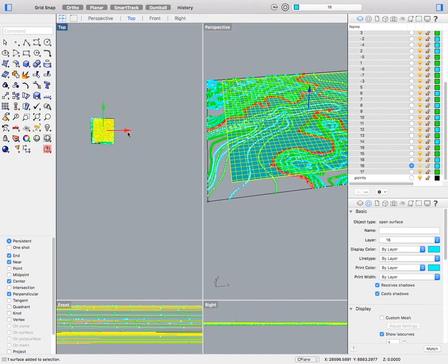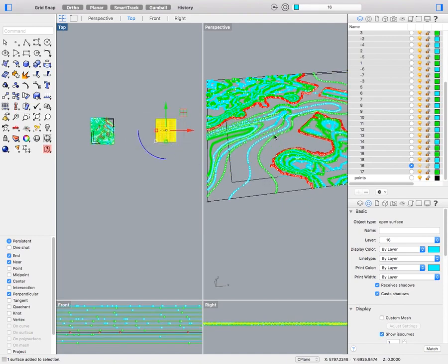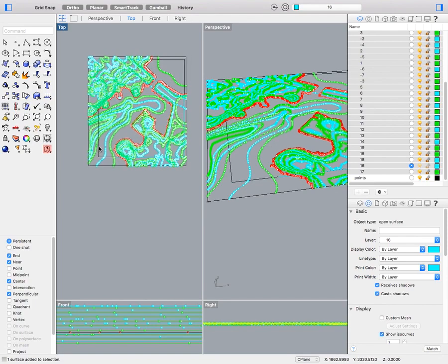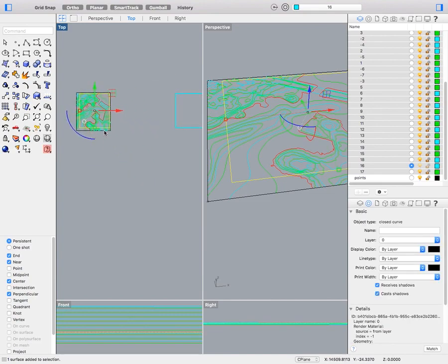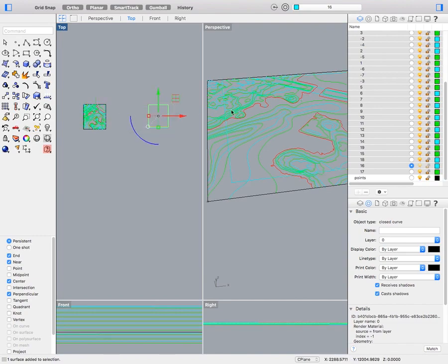I realized that this file that I gave you, the units are wrong. Oh, okay. There is some discrepancy within units. This is in millimeters, so when you go up 2, it's only 2 millimeters, where in actual fact, each contour should be 1,000. Yeah. Okay. That's good. We won't blame Jeff for this, but it's not the right model.